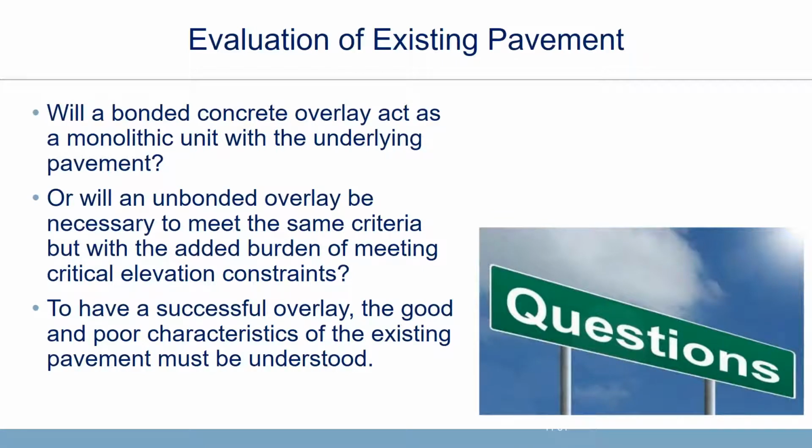Questions that you might also consider. Will a bonded concrete overlay act as a monolithic unit with the underlying pavement? Is that going to be good? Or does the underlying pavement have cracks in it that you don't want reflected up into the overlay? If you choose a bonded overlay, they will reflect.